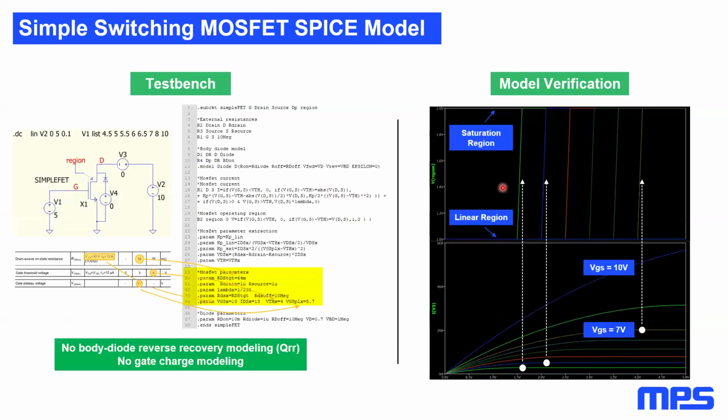In addition to the vendor's SPICE level 0 model, we wanted to propose also a further approach. In practice, we have attempted to create our own MOSFET SPICE model, including the effects that are the most relevant to the power dissipation estimations. One main driver for the creation of this model was the need to determine the operating region during the operation.